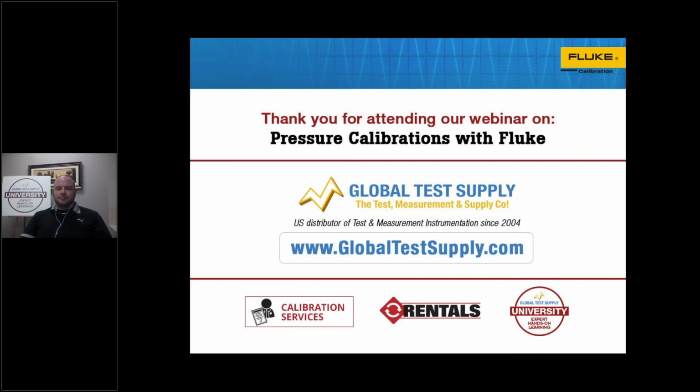If I had it spec'd as percent of reading, that accuracy might be higher than 1% of reading. Say it's 2% of reading. At 300 PSI, that means it's 300 plus or minus 6 PSI, but down at 10 PSI, it's 0.2 on either side. And so understanding your accuracies and how they play with each other across a range is important. I guess the takeaway is it might not be able to, it could do it. It really comes down to doing the math.